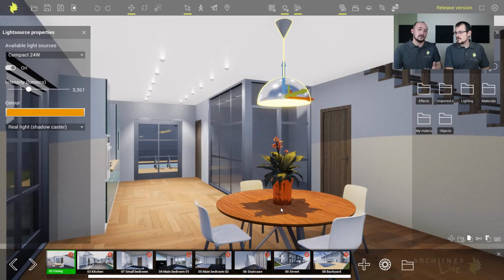So that is a little bit more realistic, but you should not turn all the light sources to real lights, only those that have a very important visual effect on your drawing, to keep the cost of the calculations low. In that case, you will have a nice and fluent workflow. I think that applies to everything. Just furnish and elaborate those things which are in focal points.